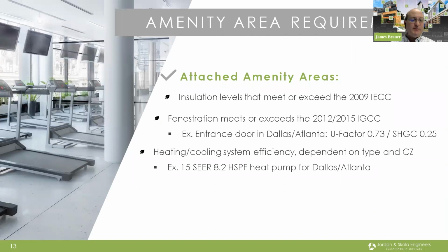So for your attached amenity areas, your insulation levels need to meet or exceed the 2009 IECC. The fenestration in these areas needs to meet or exceed the 2012 or 2015 International Green Construction Code. Now, some people might not be familiar with that, so I've included an example.